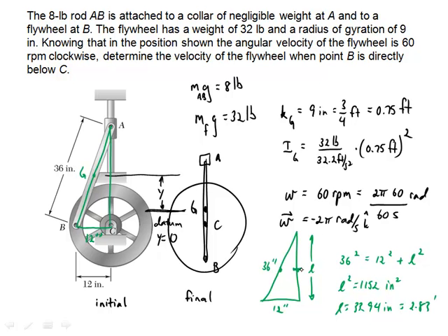And so halfway up there, and again that's above C now, so it's half of that distance from C up to where the center of gravity is. And the bar is 36 inches tall, so from C to the center of gravity, this is 12 inches, so this must be 6 inches between these two. So the datum is 6 inches, which is a half a foot above C. And half of that distance is the distance above C. So then we'll subtract a half a foot from there. So y would be equal to 1.414 feet minus a half a foot, which is 0.914 feet.